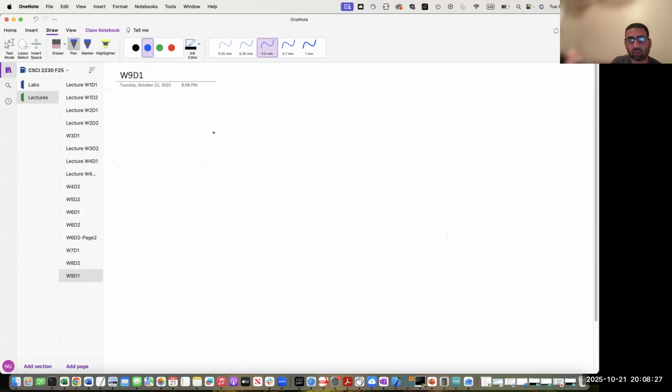So how can we visualize it? For example, let's say this is your microcontroller, and this is ADC0, and you have selected in the MUX register that you will read the value from this line. Then in your control register, you set AD enable equal to 1, and then AD start conversion equal to 1.